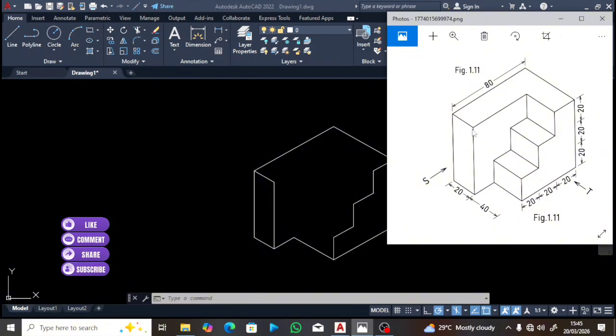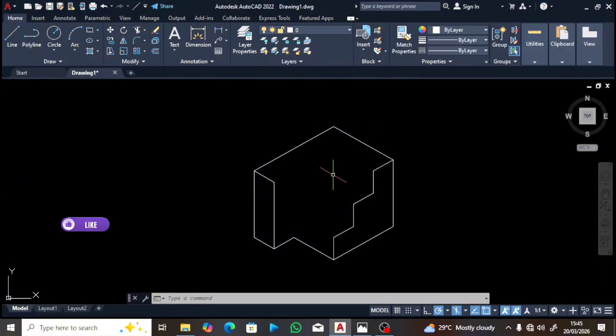I will come here by what? By 60. Then join it to this point. From here, I will come like this by 60. Then join it to this point. Okay. So let's do that. Pick the last command. You can come here to pick it or click enter, since it happens to be the last command. So come here, click on that point.